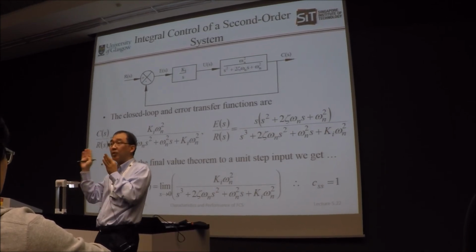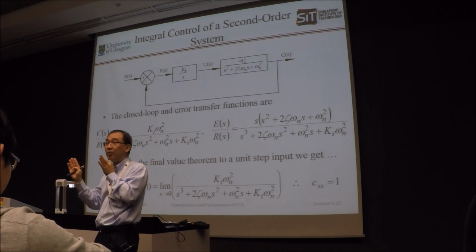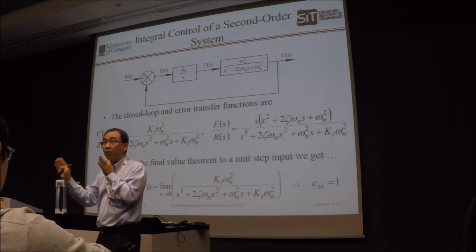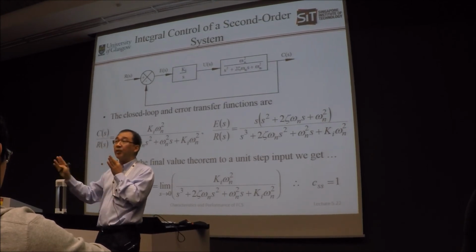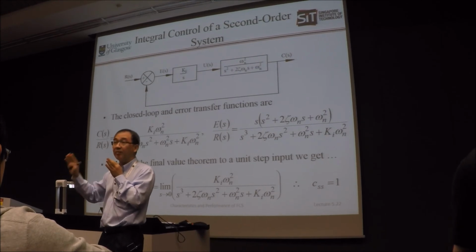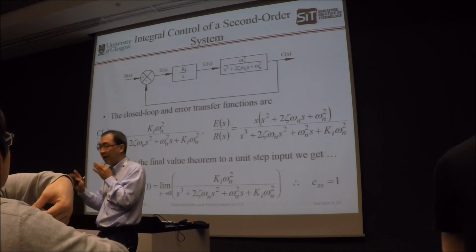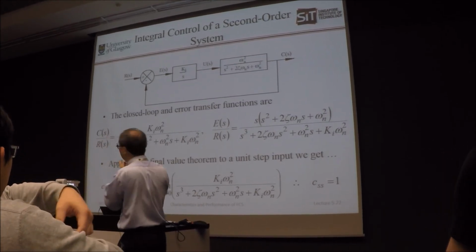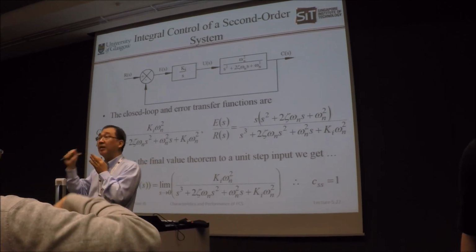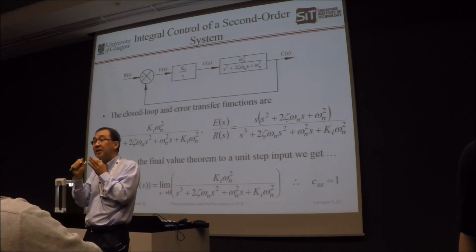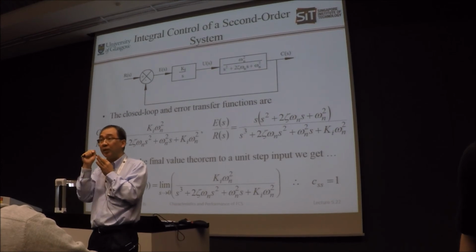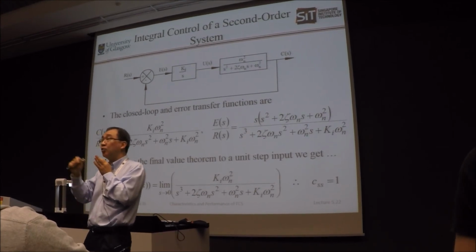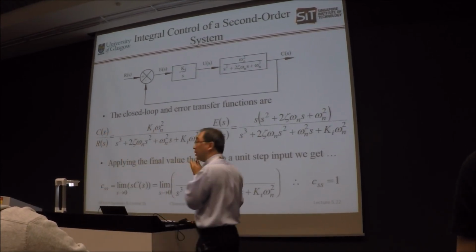For a first order system, you will not run into stability issues as long as you're using time domain analysis. If you're using frequency analysis, yes, the system can actually be destabilized. But applied to a second order system, that is very real. If you're not careful with tuning your Ki value, you do run into an instability situation.